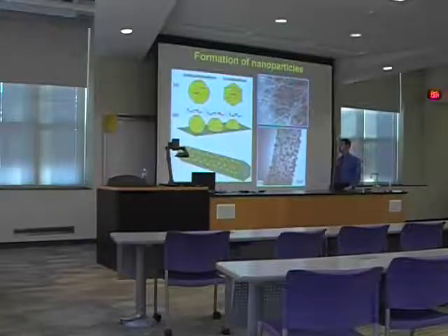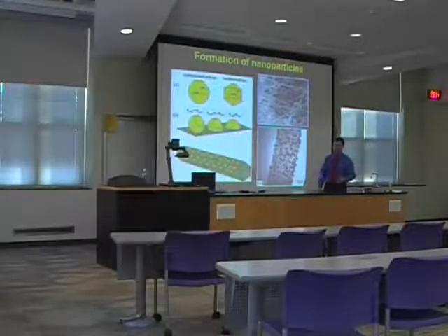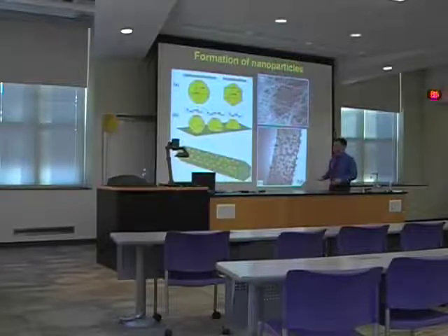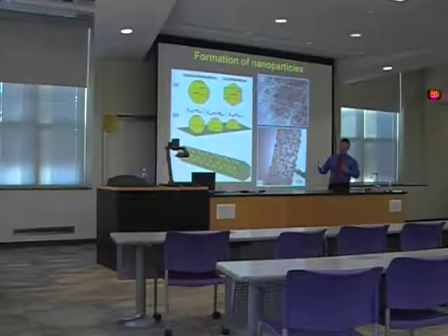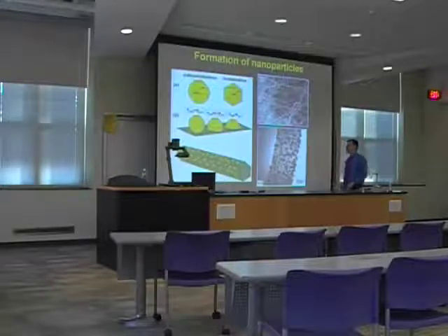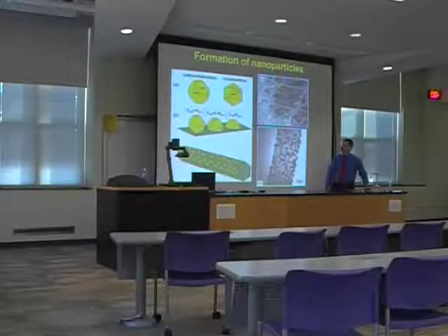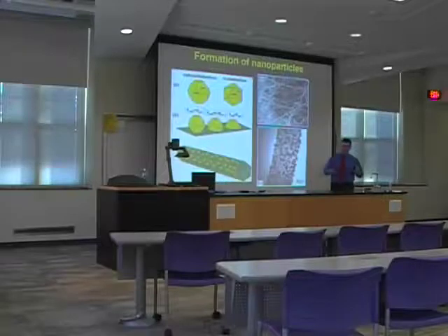So to measure these changes, to turn them into electrical signals, to analyze the environment, we should put these nanowires, or mat of nanowires, into an electrical circuit. Obviously, you inject some gas. This gas will affect the surface of nanowires, change electrical properties. We will see it as an electrical signal. However, there is a certain difficulty with gallium nitride nanowires because they're very chemically inert, so they normally ignore chemically active environment. So we need to activate them somehow, to functionalize them.